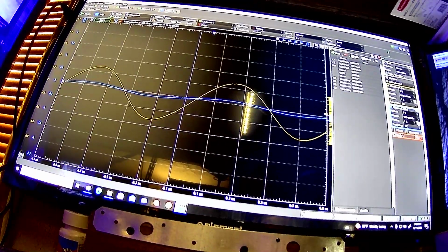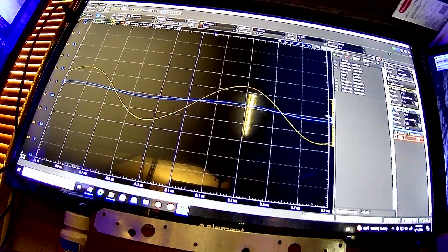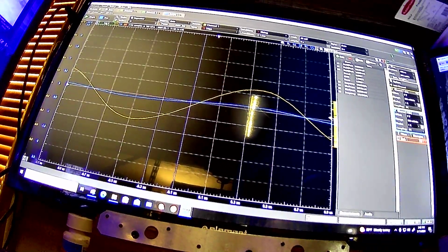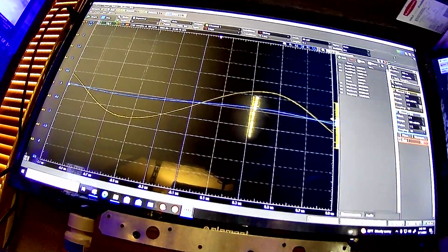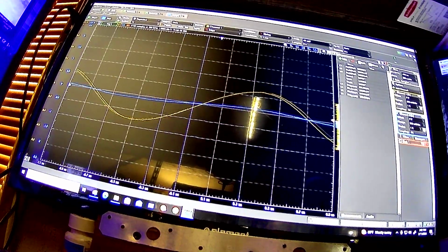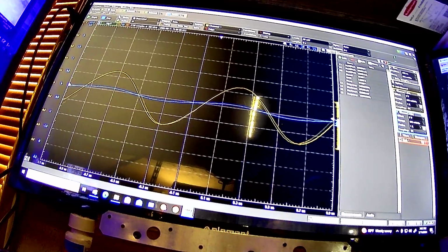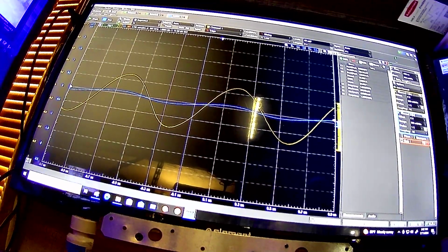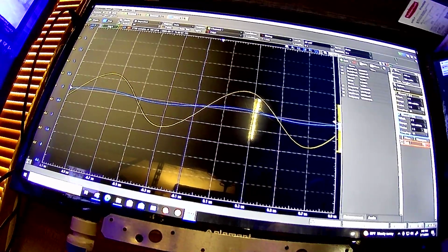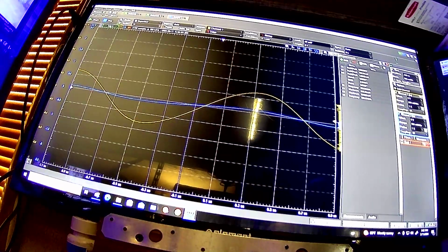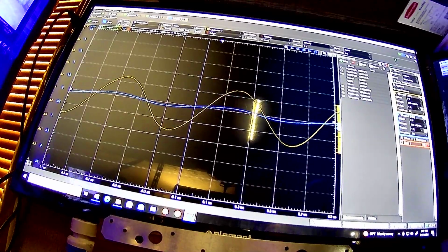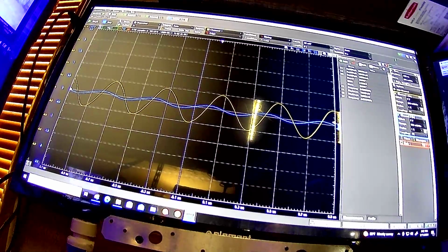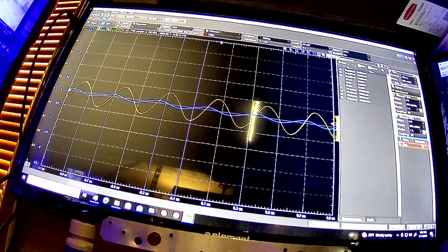So we got increased gain, but then we go down to 600 kilohertz. It's still a gain of 3 point something. Even at 600, it's a little over 3 now. But, yeah, it's about 3.3, right at 1.24 megahertz or so. So, it seemed to confirm that, but I don't really see a lot of evident distortion at this level, although it does look kind of slightly distorted.